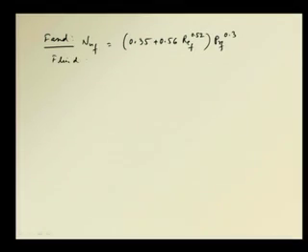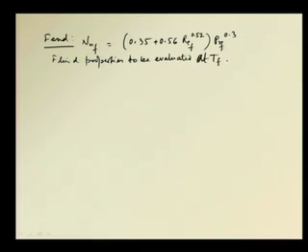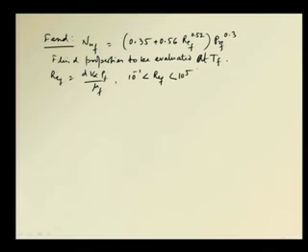That is the indication of the suffix F here, and Re_F is again D V infinity rho by mu, with these properties at F. F indicates that they are to be evaluated at film temperature, and 10 to the power minus 1 is less than Re_F, which is less than 10 to the power 5. Again, this Reynolds number is based on the diameter of the pipe.